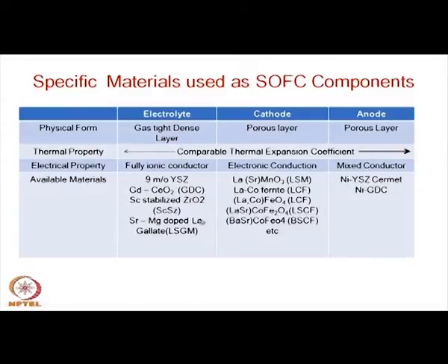Strontium and magnesium doped lanthanum gallate. Lanthanum gallate is another compound which is supposed to have a very high oxygen ion conductivity, quite high compared to YSZ or zirconia. Even at 100 or 150 degrees lower, you have the same kind of conductivity that you get with YSZ at around 900 degrees centigrade.